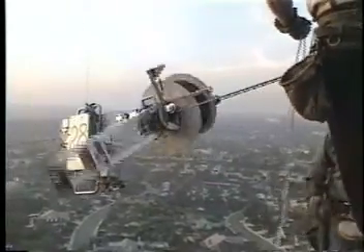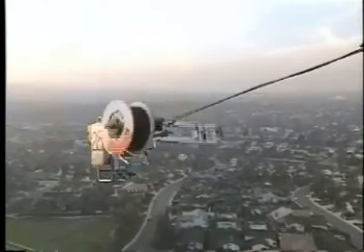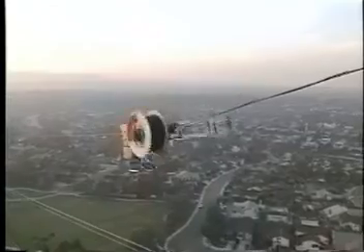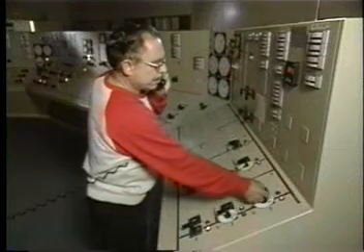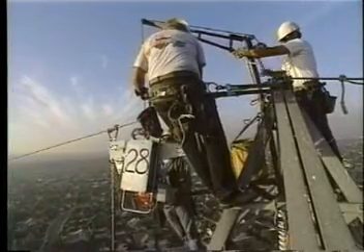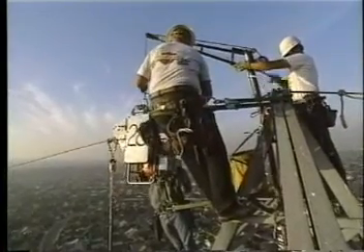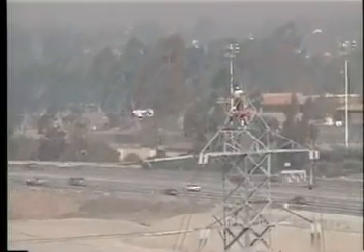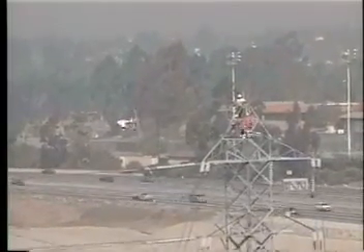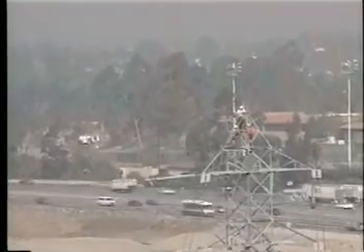To install wrap-over phase cable, a cable reel is mounted to a wrapping machine which is pulled along the conductor by a remote-controlled tugger or pulling line. After powering down the transmission lines, the equipment is first hoisted into position over the conductor using a small boom and pulleys. To place a section of cable, 2 machines are sent out from a starting tower called the spin point. One half the cable is paid out in each direction.